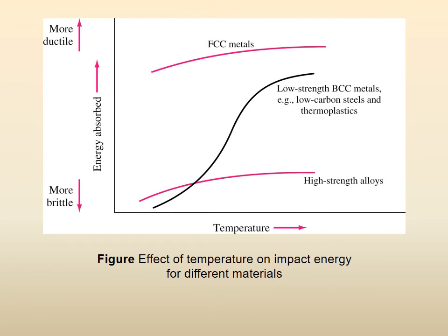Now, the first slides about the Titanic, right? Now let us see what we are showing you here. Here it is the impact toughness, the energy absorbed. If the material can absorb more energy before it fails, it is ductile. And if the material does not absorb too much energy, suddenly fails, it is more brittle. So if the impact energy is low, right, it breaks at low energy in the impact machine, then it is brittle. And if it takes a lot of energy before it breaks, it is ductile.